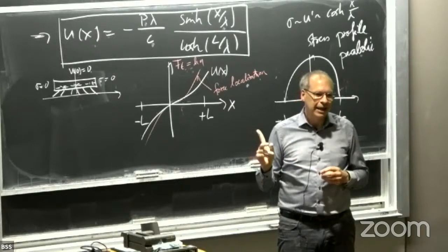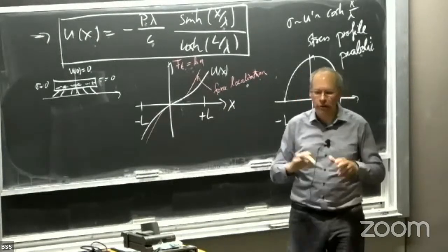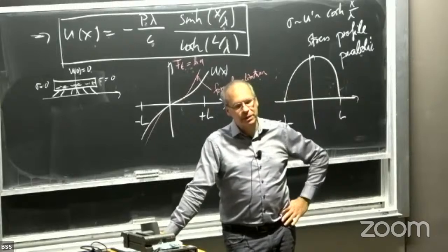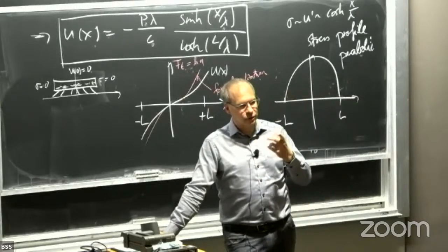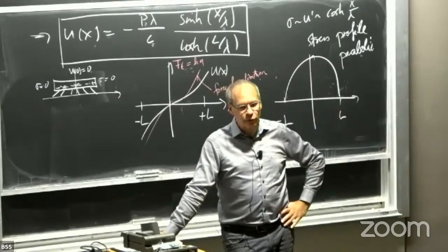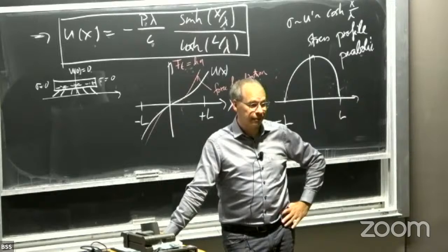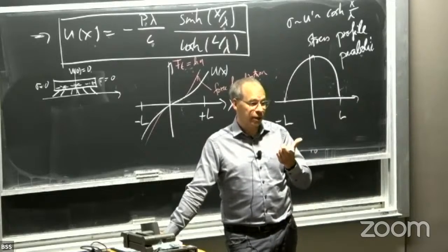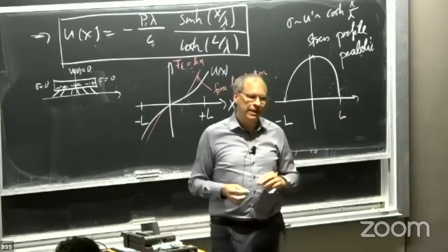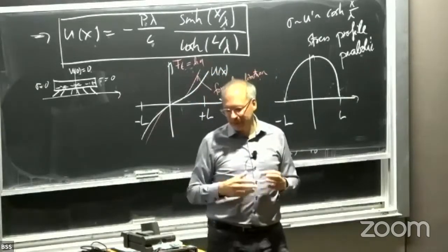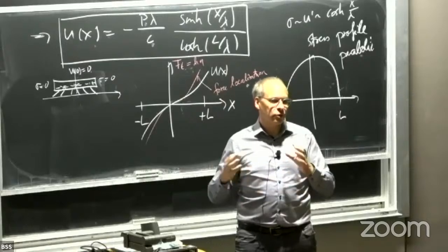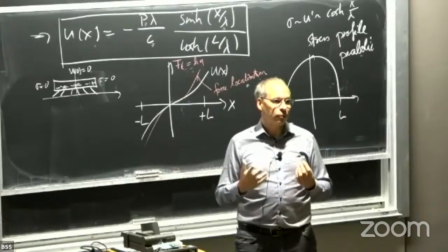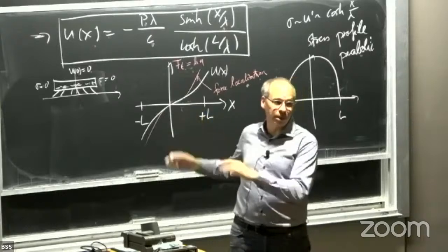So everything remains. So yeah, we wrote down, of course, and Sheila also, we wrote down the full equations and they are in my notes, but I'm not sure if I will be able to show them. So in principle, if you go to higher dimensions, 2 or 3 dimensions, the first thing which happens is that you get more elastic moduli, okay? But if you stay with the isotropic linear approximation, you only get one more, which is the Poisson's ratio, and this is always 0.5. So it doesn't make a big difference. However, if you now say that this is a more complicated system, like a nematic, you have to introduce a nematic order parameter field, the Q tensor and things like this. So then, of course, it gets more complicated if you give it more internal structure.